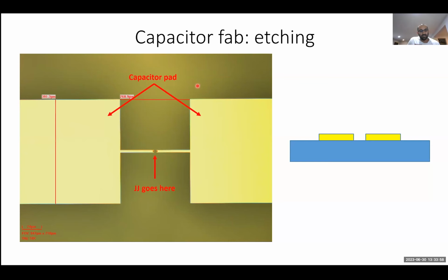Fluorine-based processes can etch aluminum and its oxides, and sapphire is aluminum oxide. And given that we work on sapphire, we would rather use a fluorine-based process in order to eliminate any possibility of potential interaction of our etching with our substrate. The reason why aluminum doesn't interact with fluorine-based processes, I don't know the specific reason. It probably has something to do with the surface chemistry of aluminum.